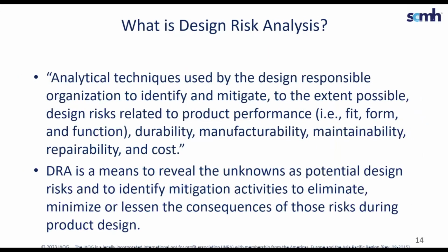So now that we have a better understanding of design risk, what is design risk analysis? Shown here is the definition of DRA, which will be in the upcoming revision of 9145, currently going into ballot. DRA is a means to uncover the unknowns and take action to mitigate those within a design. The basic objective of DRA is to ensure rigorous and thorough exploration of the knowledge and design spaces to support the identification, mitigation, and management of design risks, and provide accurate and timely flow down of product critical items and product key characteristics to the next phases of APQP.